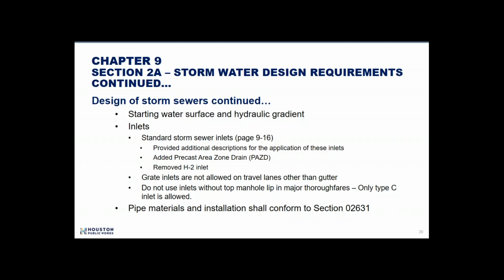So if you do two grates, you'll have basically a V in the middle. You can see the detail. The V will be in the middle of the grates. So one grate will be on the driveway upslope, and one grate will be in the gutter. And that's allowed. That adjustment will be allowed wherever it is.